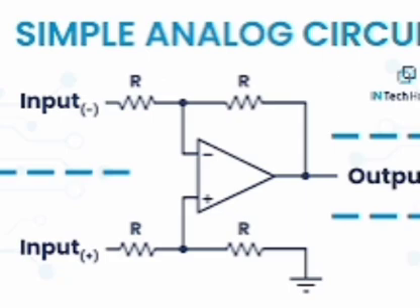Upper cutoff frequency of the overall configuration is FH star equal to FH into root over (2 power 1 by n minus 1). For identical amplifiers in cascade, FH star equal to FH root over (2 power 1 by n minus 1), where n means number of amplifiers in cascade and FH means upper cutoff frequency of one amplifier. Lower cutoff frequency of overall configuration FL dash equal to FL by root over (2 power 1 by n minus 1).